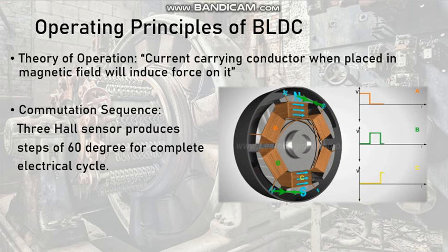One of the Hall sensors detects the rotor has turned 60 degrees, and it de-energizes the specific coil and energizes the next one in the sequence, which again causes the rotor to turn 60 degrees more. This process keeps on going, and we obtain voltage from 3 coils, as we can see in this plot here. We can see that one winding A is de-energized, the other winding B will be energized, and then the winding C, and the process will repeat. Hence, it takes a total of 6 steps for the rotor to complete one electrical cycle of 360 degrees.